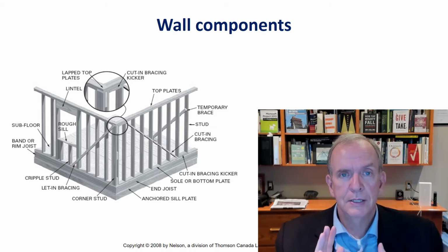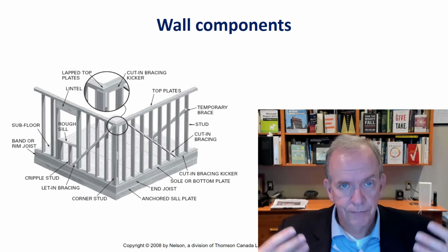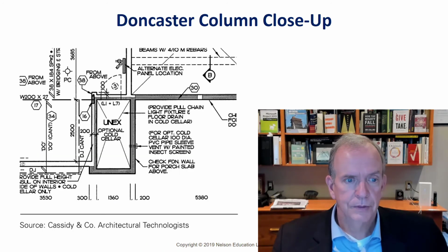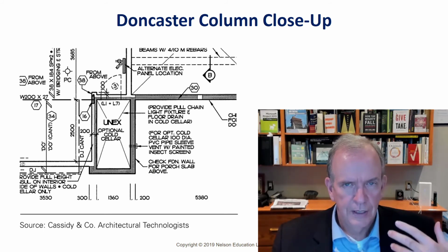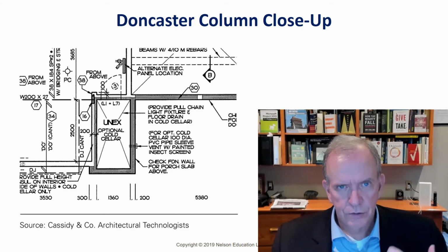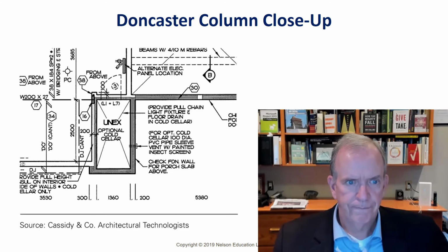A 2-stud corner makes it even better because you don't have the thermal bridging. So you alleviate the problems. It's just the way of thinking about things that you develop over time, and it's a way that if you start it early, it becomes a habit and a routine and a ritual, as I like to say.